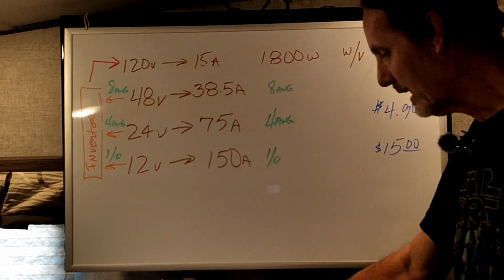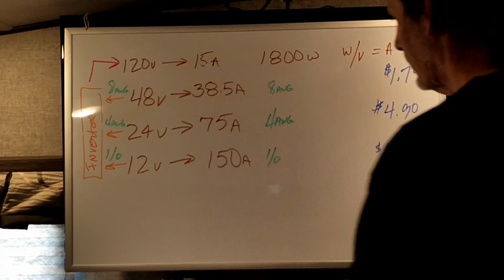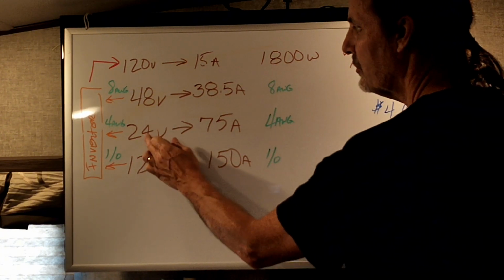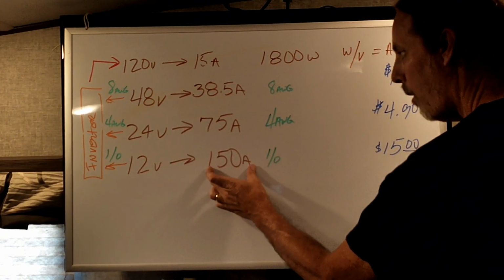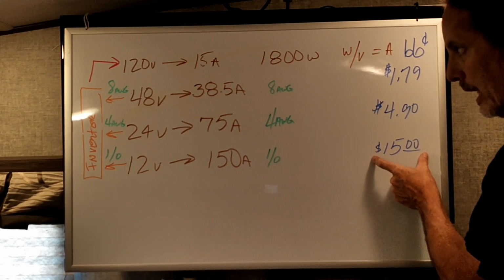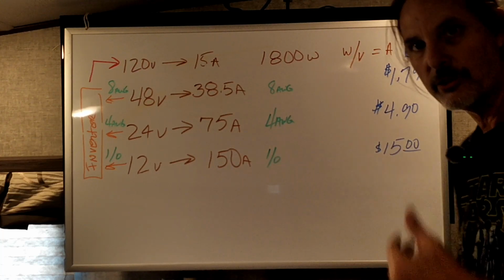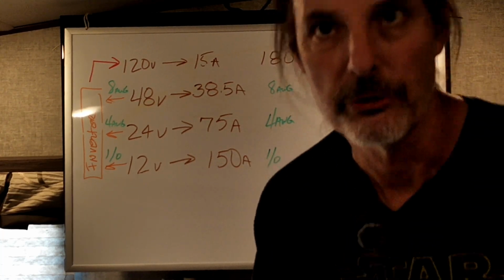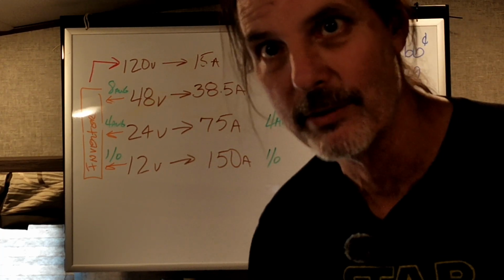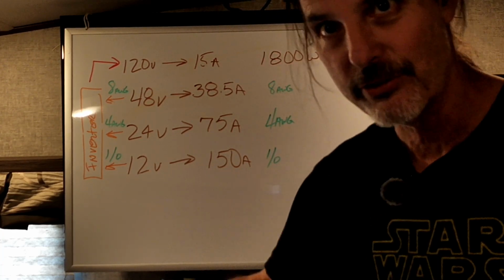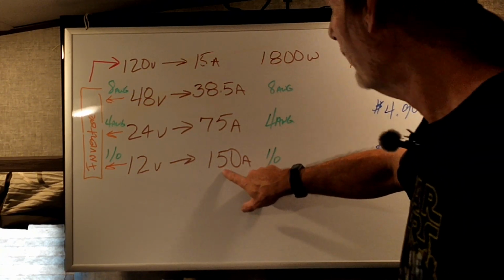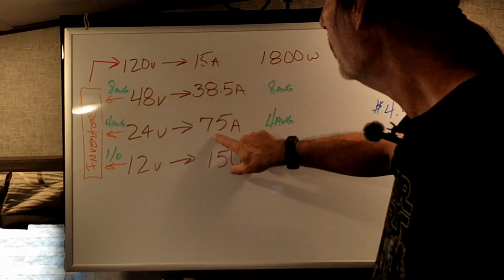So as you can see, the amperage that you need to carry in each of these systems for a simple wall plug can cost you a tremendous amount of money. And if you need more than that, then it gets to where you're going to have to run 2 of those wires, 3 of those wires. And of course, if one of those wires has a problem, then your system doesn't have enough wire to support the amperage that's there, and you end up with lots of cascading problems. So when you get an excessive amount of pull for these.